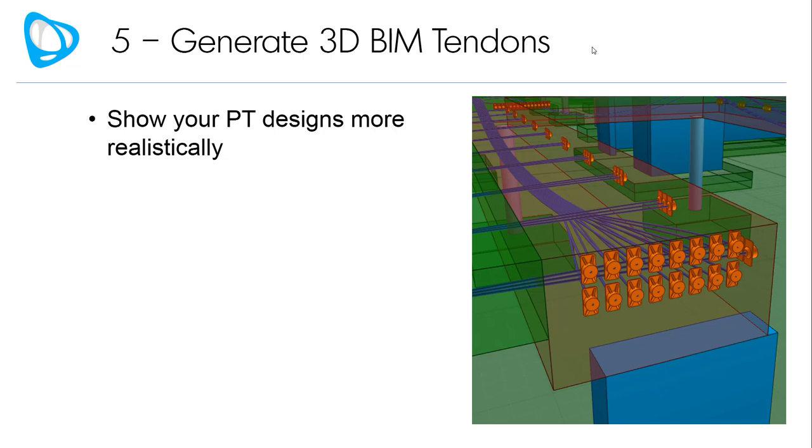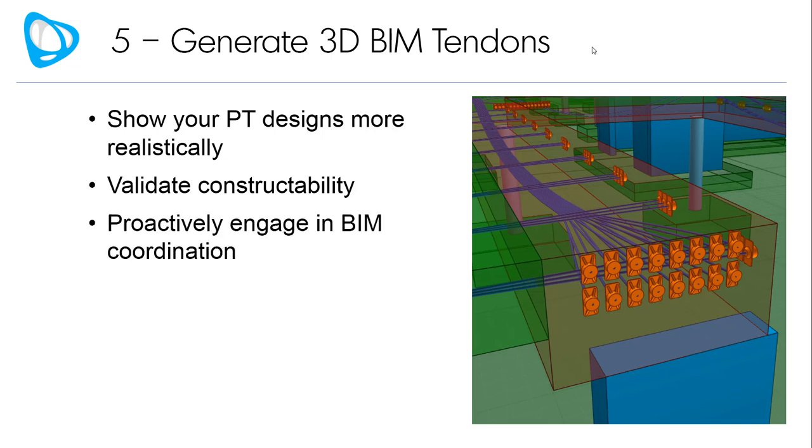of the tendons. However, we run into so many instances where what an engineer is proposing as a theoretical force, or just, let's say 21, 25 tendons in a band. That way, what Visicon allows you to do is at least order of magnitude allow you to quickly see really how much area does that take up, and is this something that may cause or trigger constructability issues. So it allows you to be able to validate constructability at an early stage of the design and be proactive